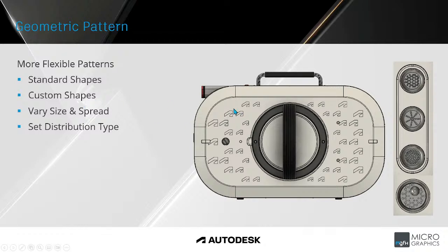So on the side of this camera that we see here, there's the Autodesk A, and that was created as a solid body in the part, which is then patterned using this tool. So you can select that as your source, and that pattern is then brought through onto the selected face. And this works as a way to distribute that pattern on the selected face. So we can see all of these, top face of the button has been selected and the pattern is distributed across.